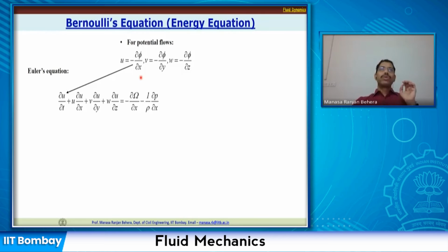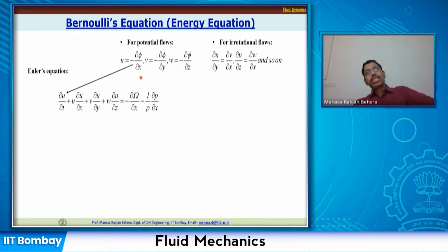So now similarly, we know the flow is irrotational. So if you write down the terminology, then we know that omega, which is the rotation, omega x, omega y, omega z, are supposed to be 0. So if you remember, omega z is equal to 1 by 2 multiplied by dou v by dou x minus dou u by dou y. If you equate that to 0, you can write down dou u by dou y is equal to dou v by dou x. Similarly, you can write down this expression: dou u by dou z is equal to dou w by dou x. Okay, so based on the irrotationality condition, we could write down these expressions.